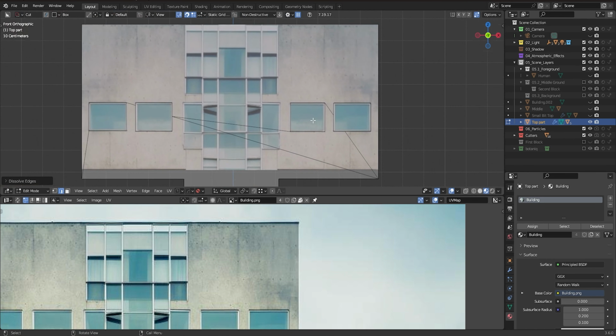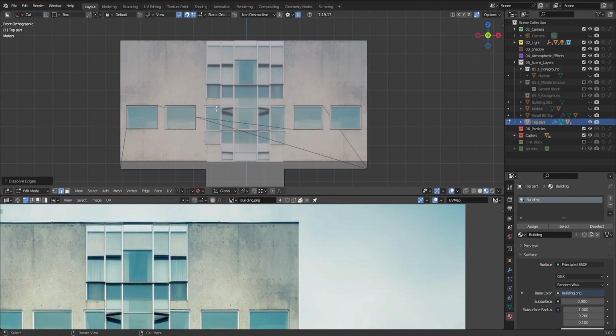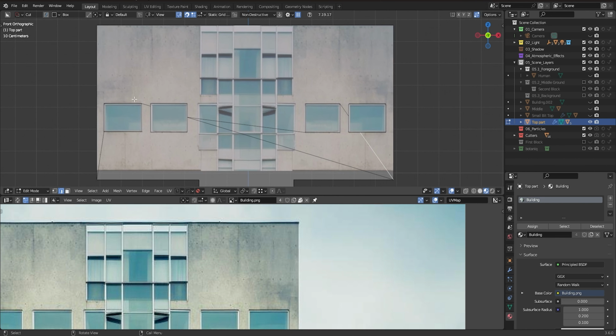Basically, when we use the knife tool, Blender, or Hard Ops, BoxCutter, I don't know who creates this, who cares, created this line here to maintain your shape, right? So you don't get distorted. And because you're doing cuts on top of each other, sometimes we don't need this extra line. So that's basically what I did here.